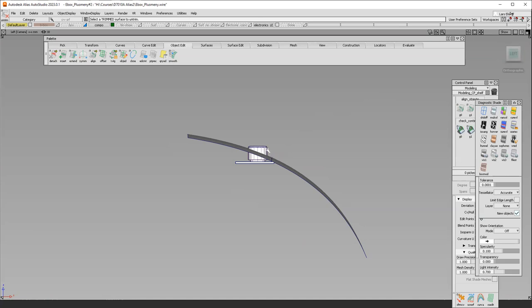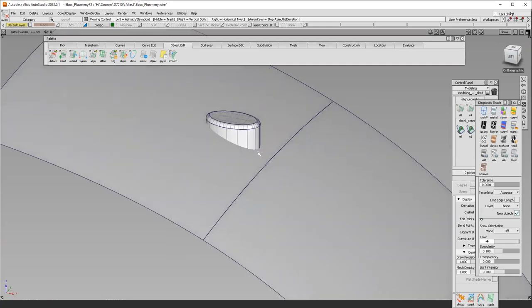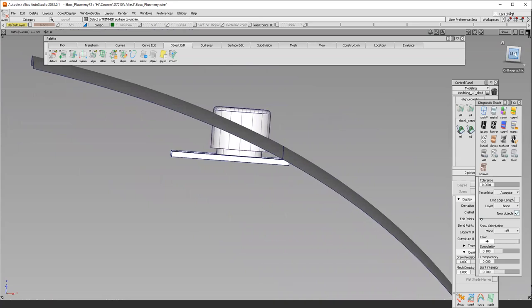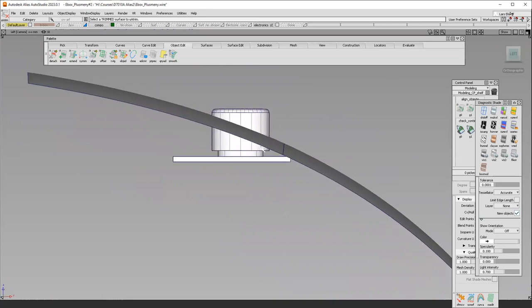It's sticking out of the surface, which is rather steep. Now, in order to get a really nice, snug gap around the button here, we do not want to rotate the button in order to make it fit to the top surface. Let's keep it in a strict Z direction like this. Also, you should know the pulling direction of the tool is going to be in the Z direction as well.